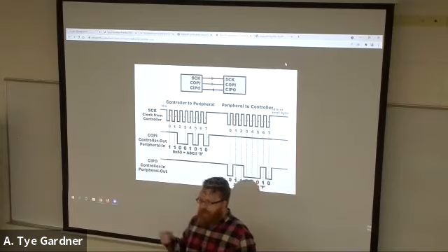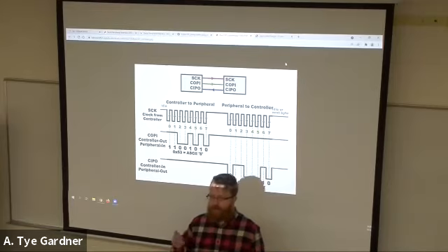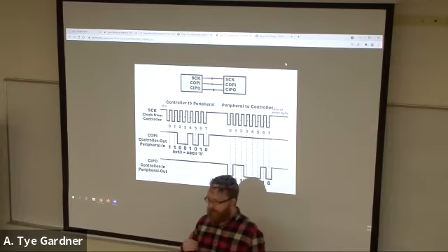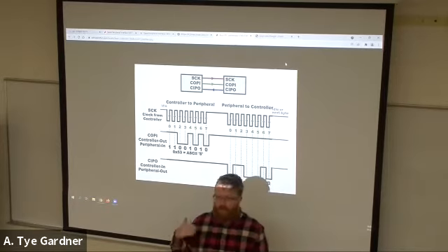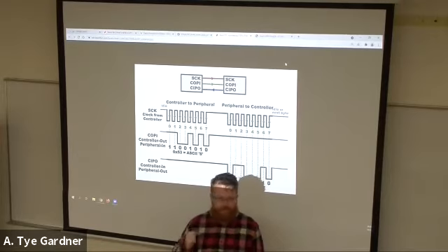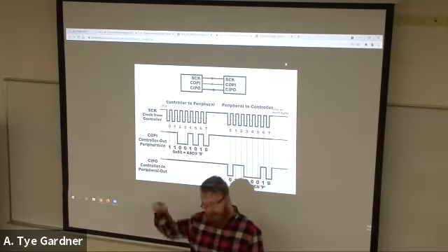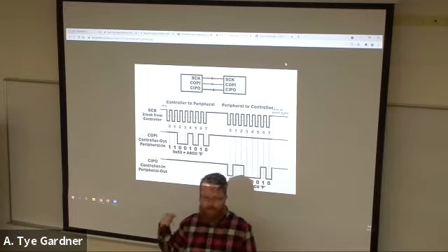UART is asynchronous. This is because it can start at any time. The receiver is just sitting there waiting for the line to drop low, and it knows that it's about to start. There is no clock for it to synchronize to. So if you run a very long packet, unless your clock is exact, which is impossible, right? You're gonna have some clock drift, then eventually you're gonna fall out of range and you're gonna start getting bad data. Eventually we'll come back around and it'll start being good data again, but you'll lose it.